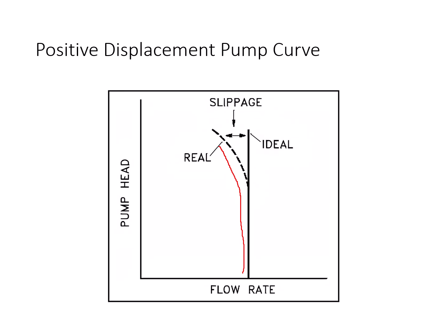This happens especially at very high pressure. In these systems, you always have to use a relief valve to protect the system from rising to extremely high pressure that may damage your pump.